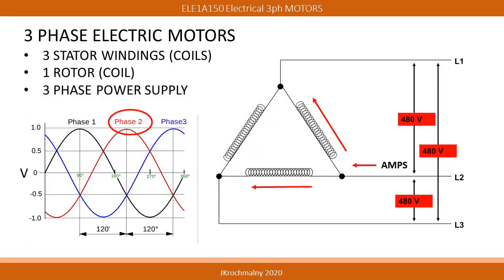Now in this graphic, we see Phase 2 voltage at a maximum compared to Phase 1 and Phase 3. This imbalance results in an amperage traveling from L2, approaching a termination and splitting in two. One amperage travels toward L1 and the other travels to L3. These two amperages are responsible for the generation of flux lines in the associated windings.